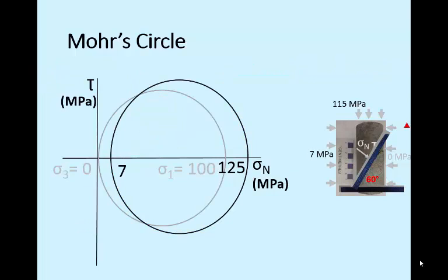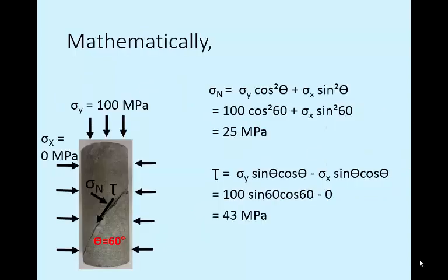Similarly, triaxial tests can be plotted the same way as a UCS test. With a triaxial test, a confining pressure is added to the side of the specimen, which is shown as 7 MPa here. And assuming that the specimen broke at 125 MPa, a plot of the corresponding circle is shown.